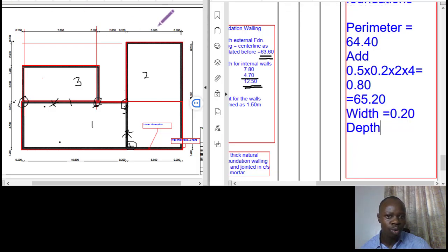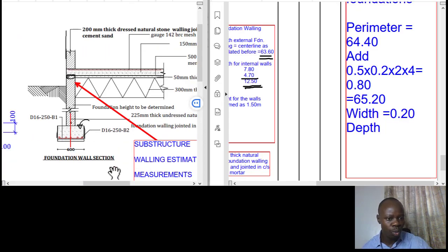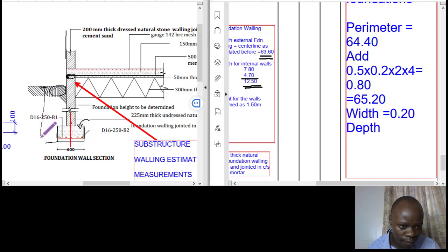Okay, so this is what we have in terms of the section. For this section, we are required to get the depth of the backfilling. You remember that there are different items that we have here. First of all, we are done stripping the topsoil, 150 millimeters, and up to this point we are going to have an item there, so we are not going to backfill the portions where we have the footing and the blinding. What that means is that when the total here was 1.5, for instance, up to the bottom, then you need to subtract what we call the top.